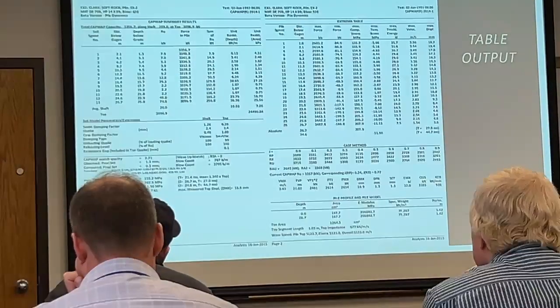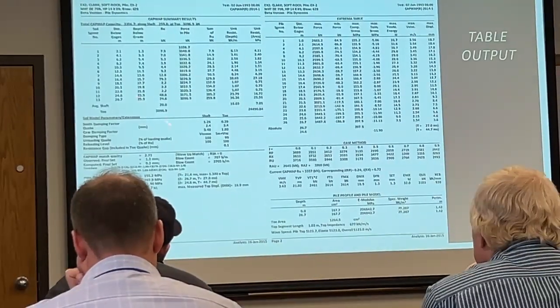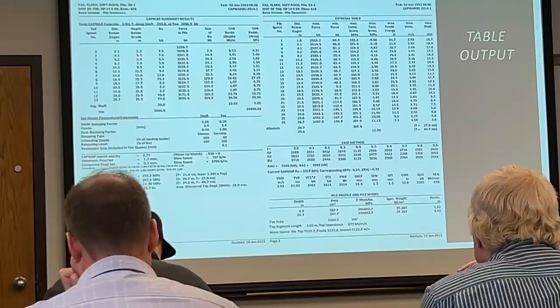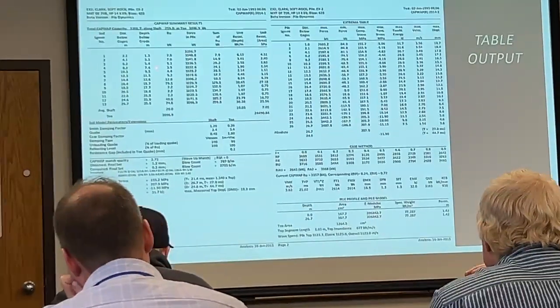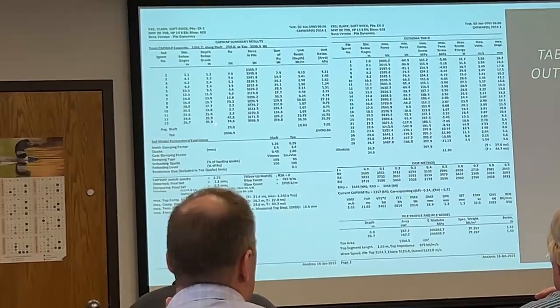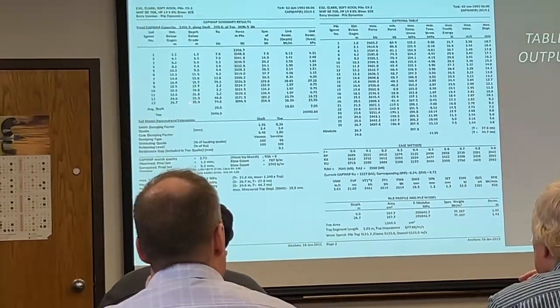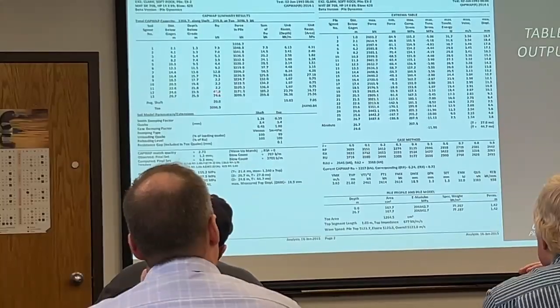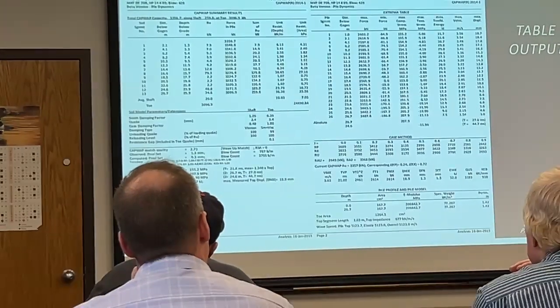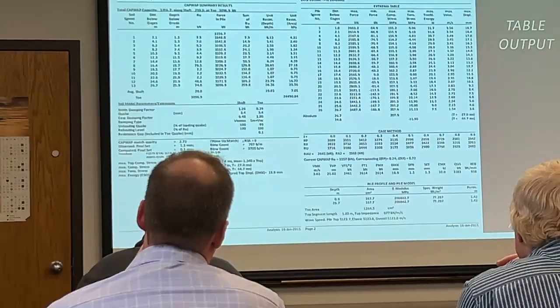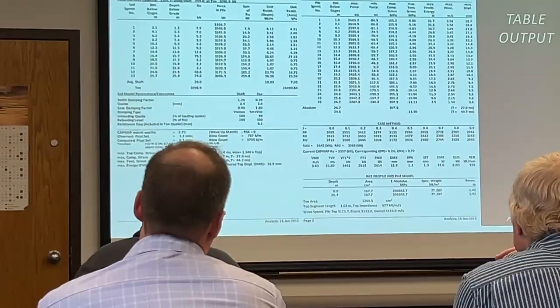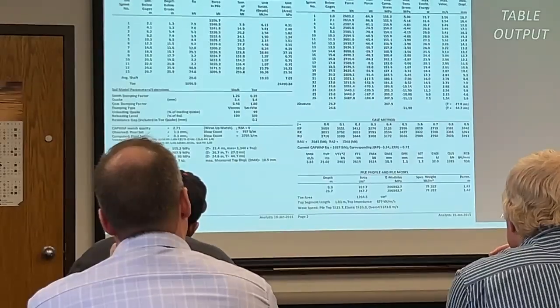We also have a set of summary results. Depth below grade is probably the interesting one. This would tell us that from 23 to 25 meters below grade, we picked up 75 kilonewtons of ultimate resistance, and that corresponds to about 25 kPa, or about 0.2 KSF of unit shaft resistance.